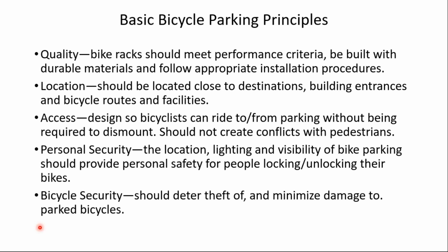Should involve also personal security, so the location, the lighting, the visibility of the bicycle parking should provide personal safety and security for the people storing or unlocking their bikes, but then also bike security, to deter theft or minimize damage to parked bicycles.